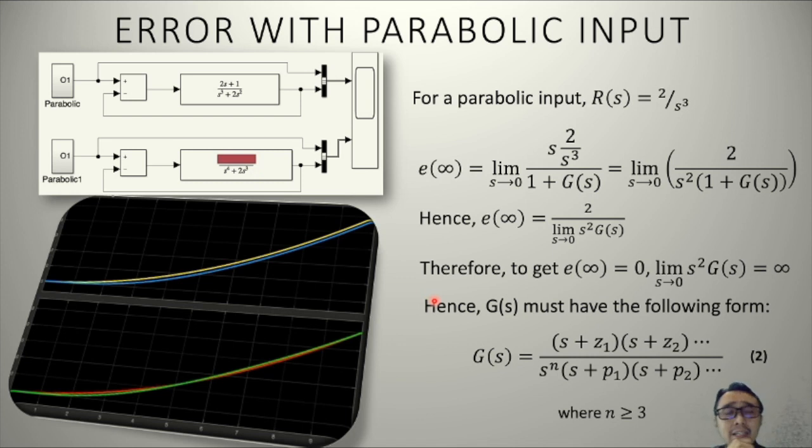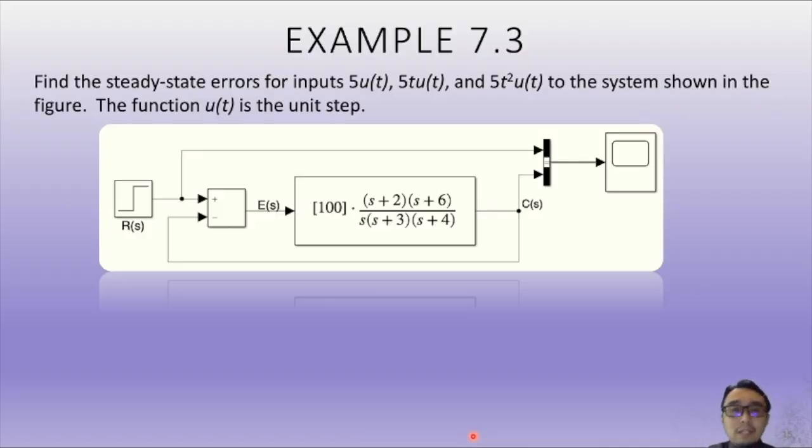But as a hint, you can just write an expression for the numerator having one or two unknown parameters, and you can use the Routh-Hurwitz criterion on the closed loop system and try to find those parameters that will cause the system to be stable. So that is one of the ways to find this unknown numerator. So please try to do that at home. Okay, finally for today,